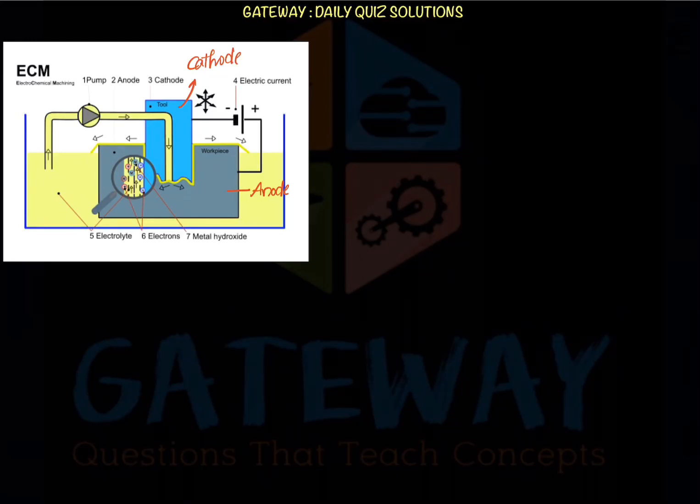Then this is called the electrolyte, which you pump through the tool into the gap between the workpiece and the tool. Generally this is our tool and this is our workpiece. In between the tool and workpiece, before the current is passed, there will be a substance called electrolyte. This electrolyte is generally a conducting material which helps in the transfer of positive and negative ions, by which ionic dissolution happens.